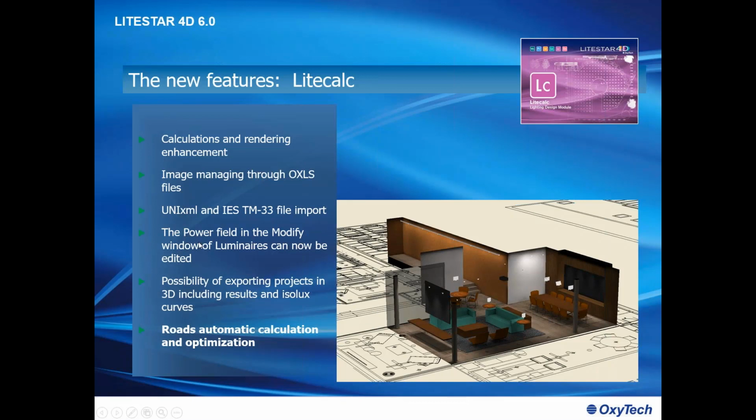This point about the power. Before, it was not possible to change the product power, the total power of the luminaire. Now it is possible. Why? Because with the LED luminaires, you know that we can manage current. And managing current, you can use a current, for example, 500 milliamp current, and you have a certain value of flux. But if you reduce the current, then you reduce also the flux.